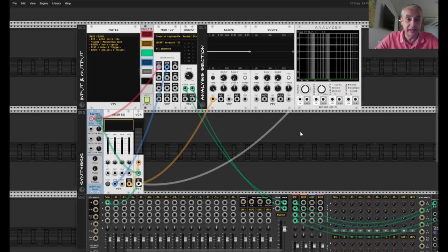But if you would agree to say, hey, I'm not going to assume 100% drop, but it could be a kind of a gradual drop, you can also achieve that by constructing something that looks close to a sawtooth, but is actually built up of a limited amount of sine waves in the right harmonic ratios. And then you come into the realm of the band limited signals, and those can be reproduced a lot better without aliasing effects. And that's what you can do with the sawtooth.